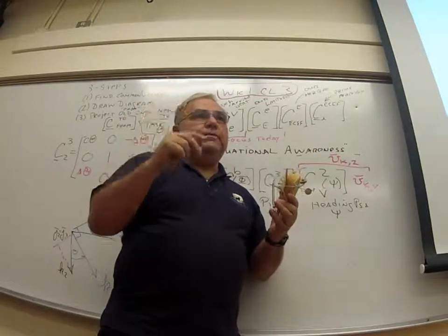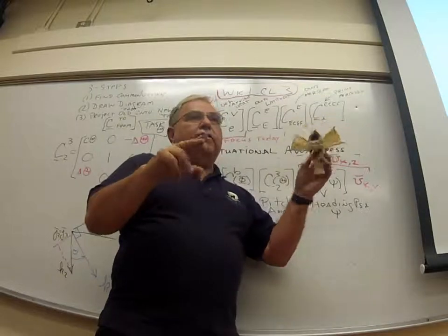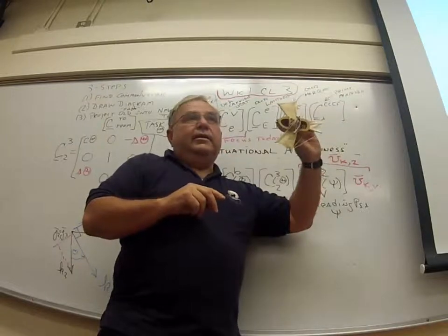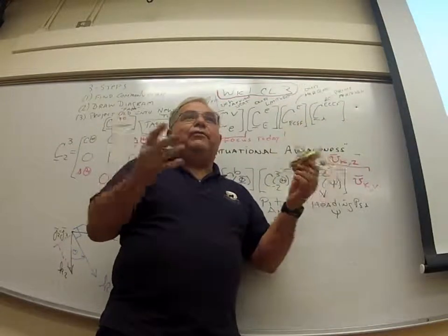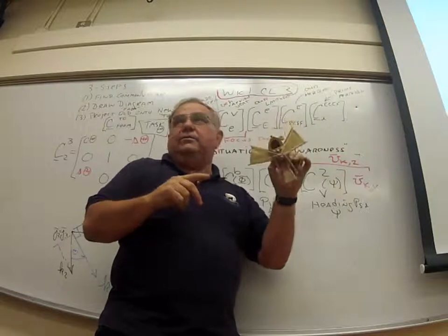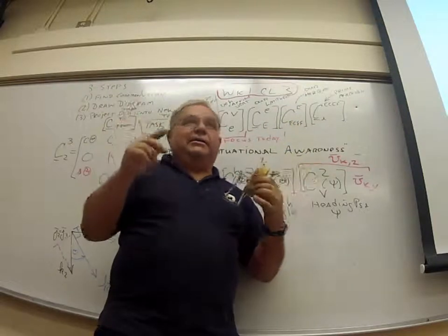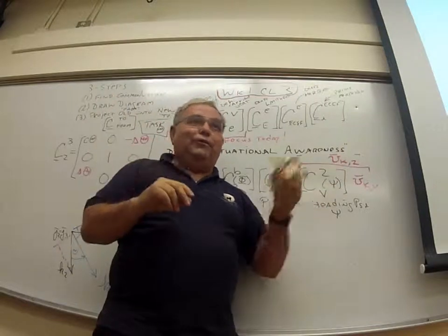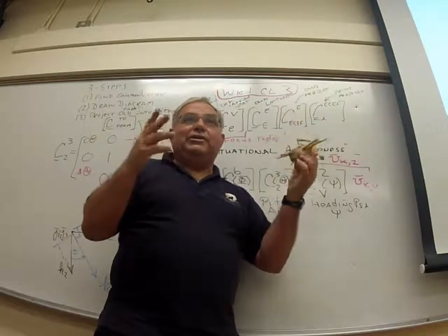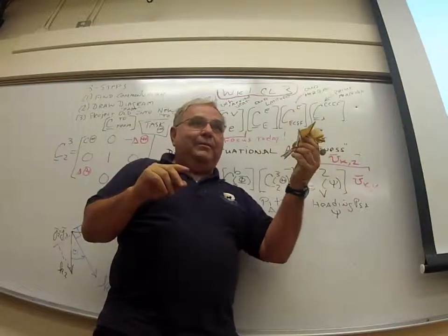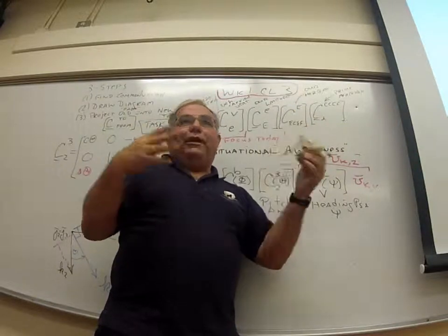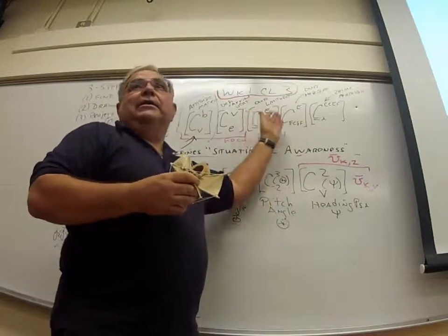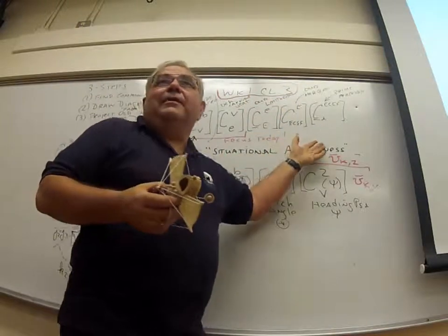Zach brings up a good point. I didn't have to go, you know, I could have gone pitch, roll, heading. You could have gone a different angle. There's 9 different ways you could have gone to get to a final attitude. And the space guys take no great pleasure in picking arbitrary ways to go from one satellite location to another one. I wish they would just use the same thing that pilots have picked, heading, pitch, roll. But they'll use alpha 1, alpha 2, alpha 3. So their direction cosine matrices will look like this, but they'll do the same thing, but they'll all have different elements in it.